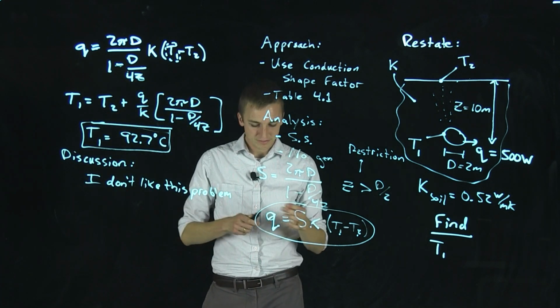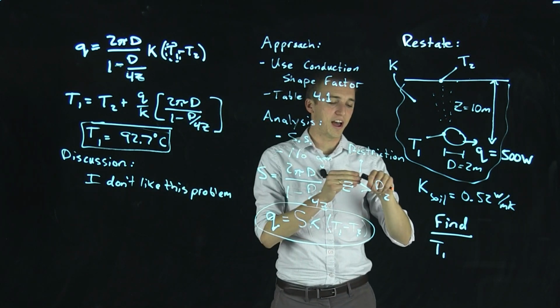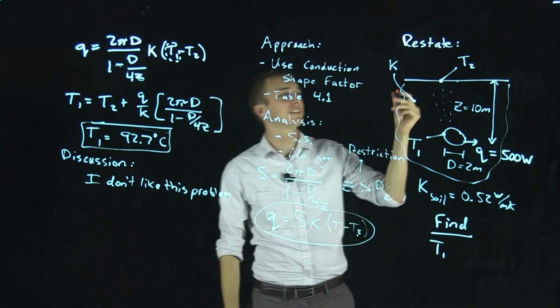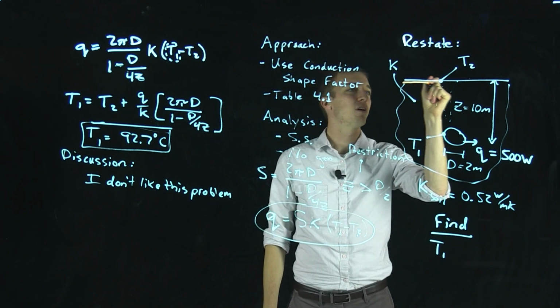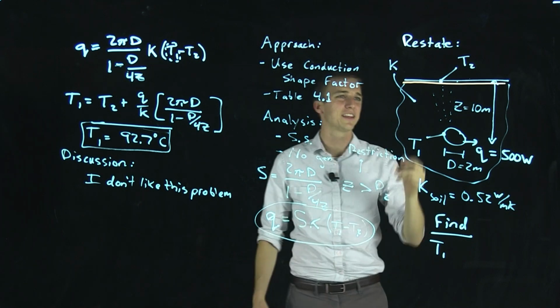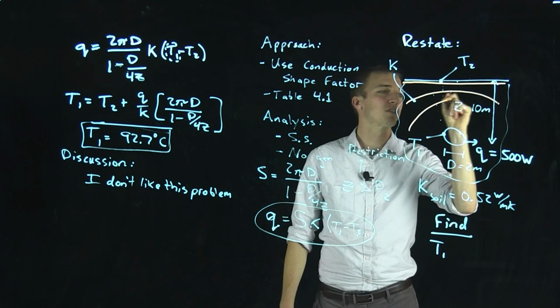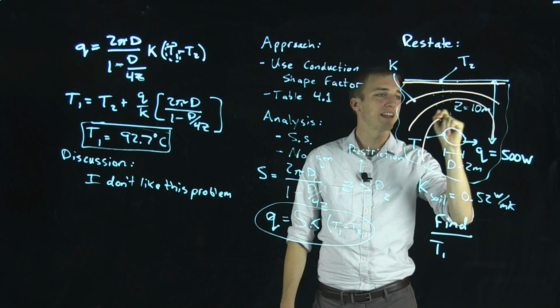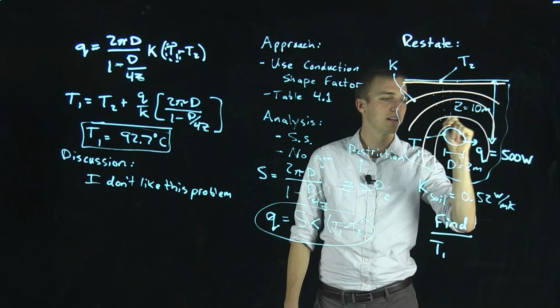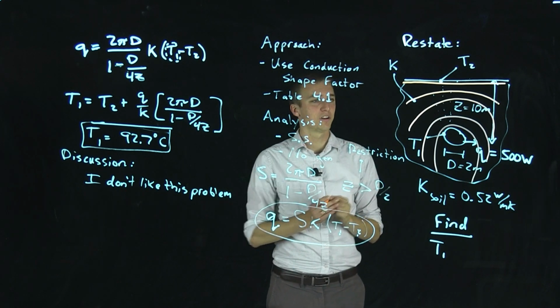Okay, our last very brief point is we are asked to draw isotherms, which are constant temperature lines. So we know the temperature of the top surface is constant, so the isotherm will look like this. Now these isotherms will begin to curl around like this, going downwards into the colder dirt below.